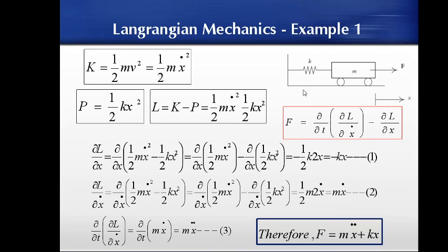Dynamic equation means the expression for the force that is being exerted on this given 1 degree of freedom system. So it seems to be very easy. The only concept is that we need to first derive the kinetic energy expression of the entire system, then the potential energy, find the Lagrangian, and differentiate with respect to the required variables. So first of all, once we get the system, list out the governing dynamic equations by applying the general Lagrangian equations,